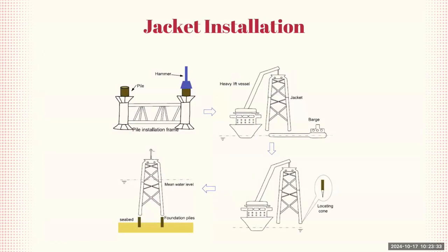Next, we have the jacket installation. So the process starts with the installation of the foundation piles, as seen in the top left diagram. The pile installation frame is used to position the piles, and a hammer drives them into the seabed.